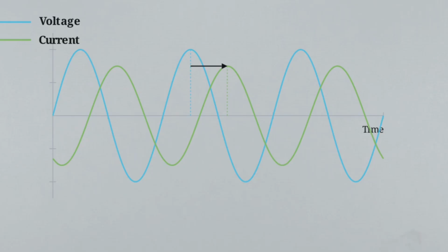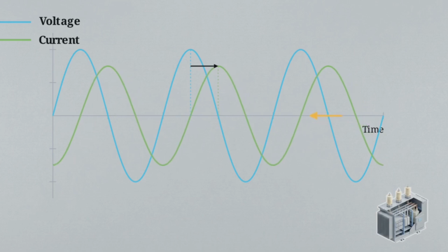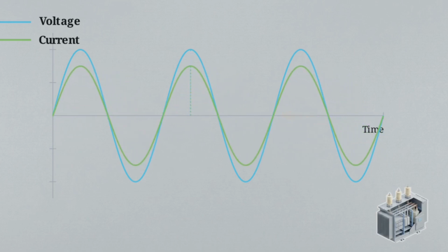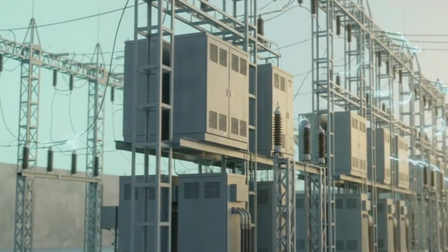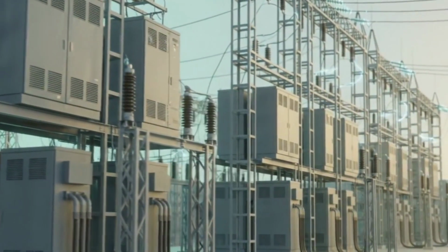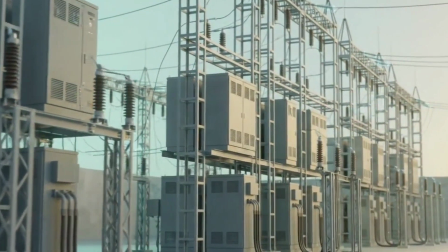To counteract this, grid engineers deploy massive capacitor banks. These banks inject an artificial, leading phase shift directly into the local grid. This calculated pulse provides the exact opposing force necessary to push the lagging current wave backward, realigning it perfectly with the voltage wave. By continuously manipulating phase alignment in real time, these large-scale capacitors optimize industrial power consumption and prevent localized grid overloads.